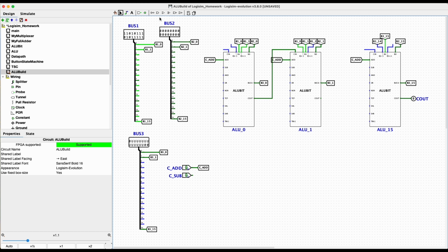So all you have to do, and the logic is kind of the same as the logic built into your lab before, is a 2 input OR gate. We'll make this a narrow OR gate. Hook it in and hook that up to the subtract operation and your 2's complement operation. That way, if they turn on subtract or 2's complement, the voltage on here will go high, and that will add 1 to your 2's complement when you're doing that. So there's that input. What about this right here?